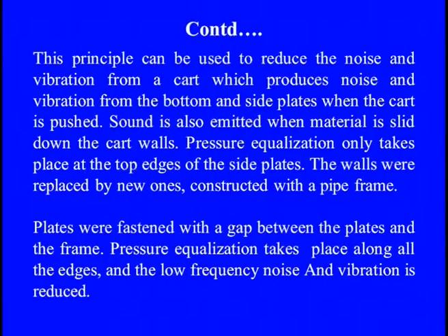This principle can be used straightway to reduce the noise and vibration from a cart, which produces a huge amount of vibration from the bottom and the side plates. When the cart is pushed, because its interaction with the ground is a rigid one, there are many variations in the forces and a huge amount of excitation. So what we can do is simply put perforated panels there itself, and we can control that.